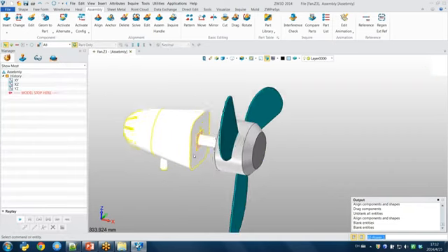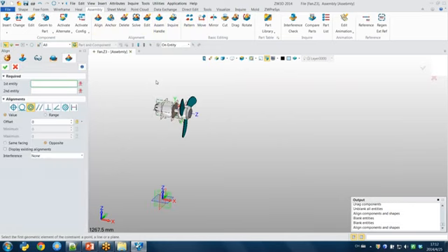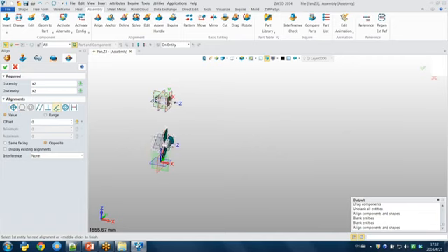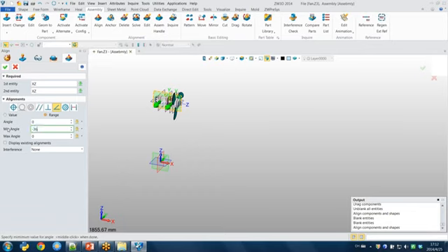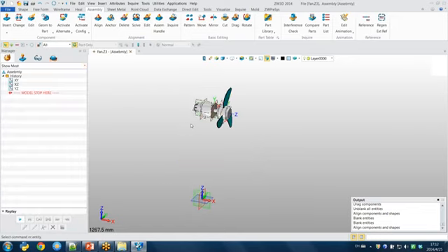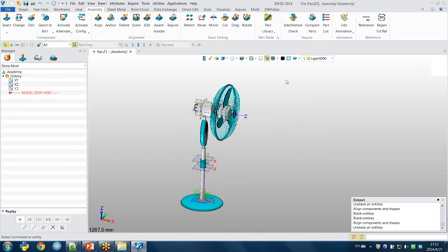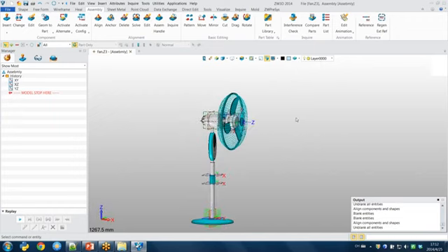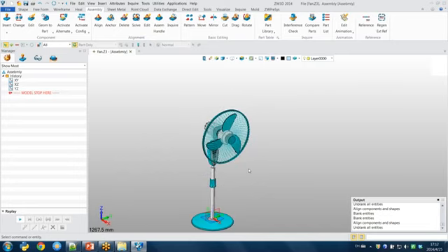Okay, so align this frame and this frame at angle. Set the range minus, and you can check. Okay, you can rotate. Press OK. After you finish the alignment, you can show all. Okay, and close the datum.